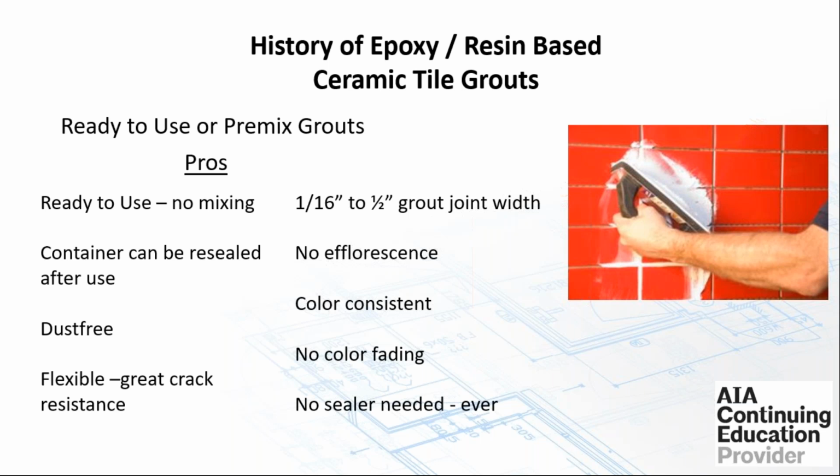Another advantage is that the container can be resealed. So let's say you're doing a project and you have some of this grout left over at the end. You can put the lid on it, and there it is, attic stock, if there's a repair that has to be done. Typically this resealed grout will last up to a year, and can be used for a touch-up or repair. And you'll have the same color, the same shading as the original installation.